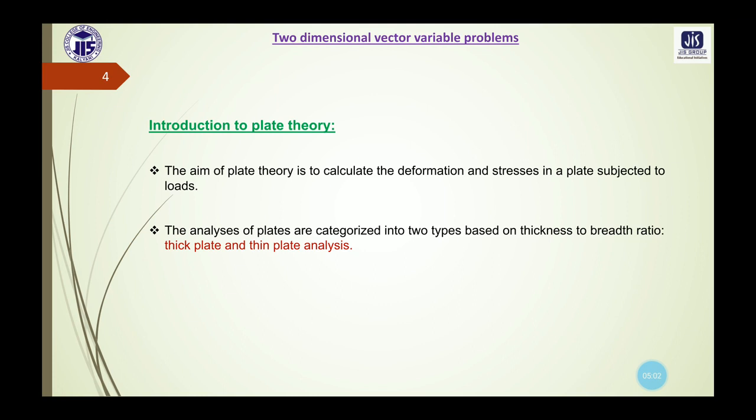What happens when some forces are applied, how the plate resists those applied forces. Now the plate theory takes advantage of this disparity in length scale to reduce the full three-dimensional solid mechanics problem to a two-dimensional problem. So this is the aim of the plate theory: to calculate the deformation and the stresses in a plate subjected to loads.